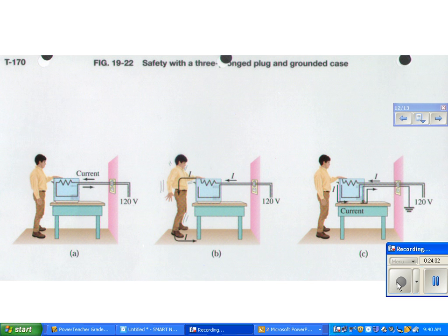very quickly. So what we've done in modern society today is we've developed a thing called a ground fault interrupter, and in those special outlets with the reset buttons, there's a magnet and some wires, and it can sense how much current is flowing. And as soon as the instant there's a spike in current, if the current suddenly goes up for any reason whatsoever, that little thing will pop and break the circuit and save your life. That's the whole goal. So notice those tend to be in places that are located near water. And hair dryers nowadays in America, most hair dryers you buy will have one built into it. It's because for some reason, some people thought it was a good idea to dry their hair in the bathtub, and that's dangerous.